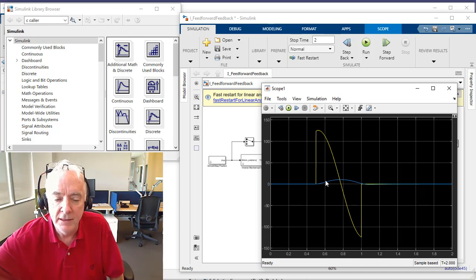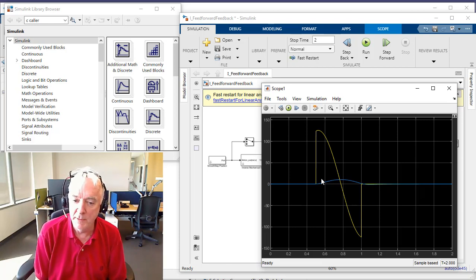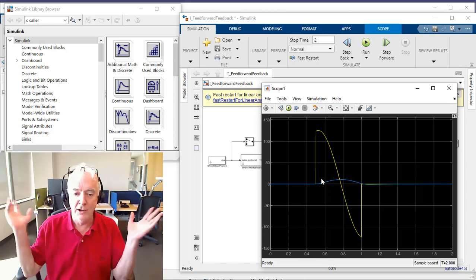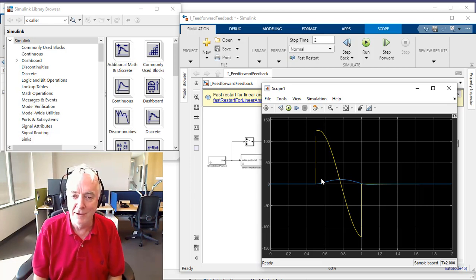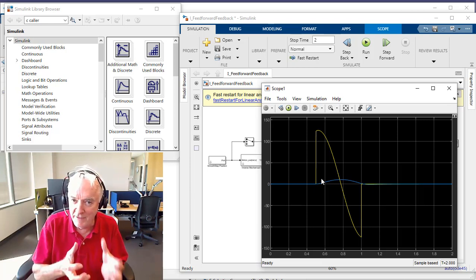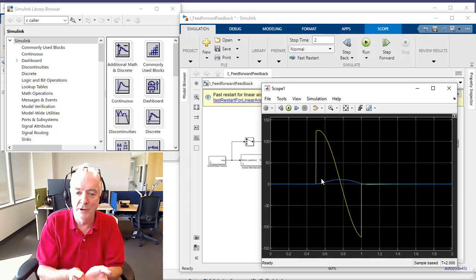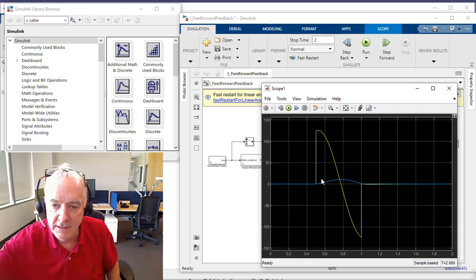All right. And what I'm suggesting is that when you begin to see that become more and more significant, that's your way of knowing. And you can apply all kinds of very clever, I'll call it numerical analysis. You might even call them AI or deep learning, machine learning type of algorithms that can look at signals like this and draw the proper conclusion. And the conclusion here might be that the bearing is beginning to deteriorate.